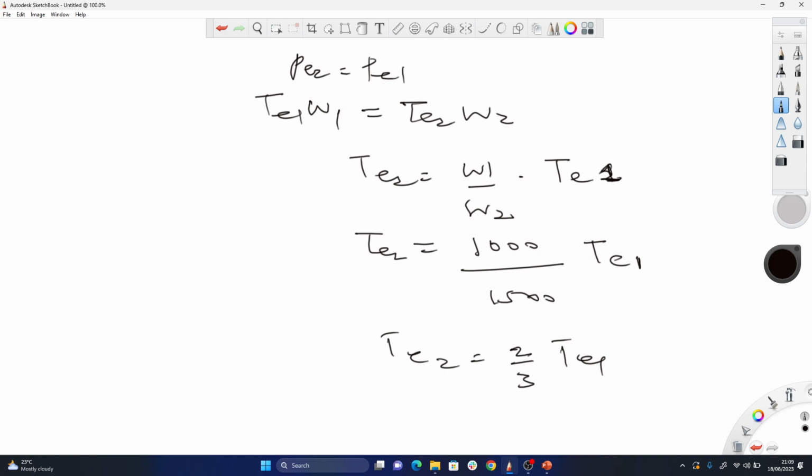Everything we've done so far, we're looking at speed control of DC shunt and separately excited motors. We saw varying armature voltage to reduce the speed, the conventional method and the Ward Leonard solid state method. Then we came to speed control by varying field current, where we saw the conventional method, the use of the field regulator and rheostat.